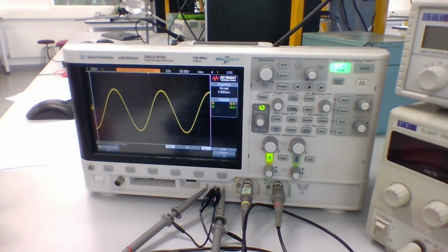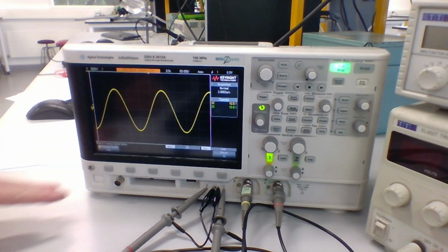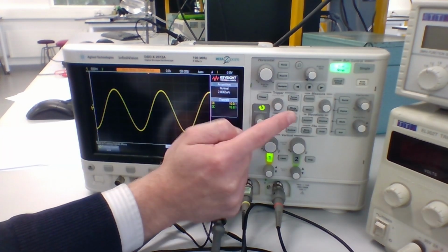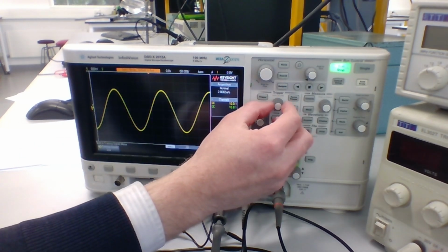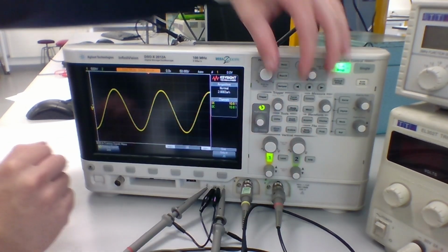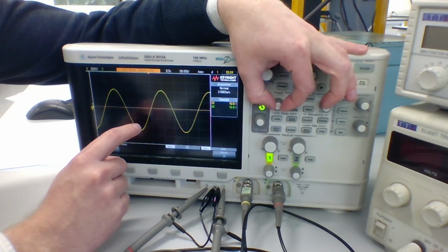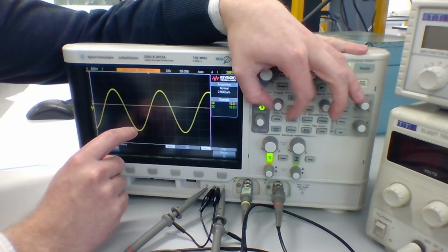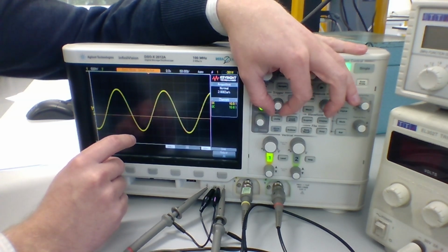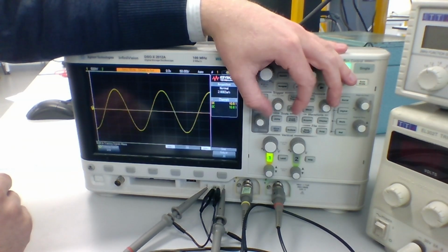We can adjust the trigger though as well. What we do is we adjust the voltage level of the trigger. So on the oscilloscope, on the front panel here, you'll see there is a button labeled trigger. We can turn this dial and it will change our trigger level. So if I turn that, you'll see a line appears on screen representing where our trigger is. As we scroll that up or down, you'll see the waveform moves to the left or the right. And that corresponds to the voltage level at which this trigger is taking a measurement.